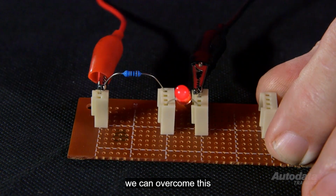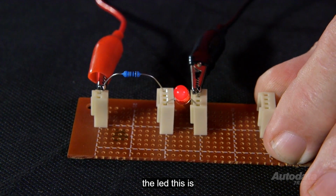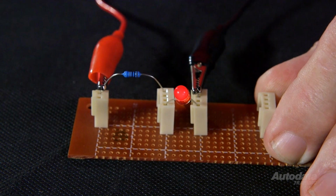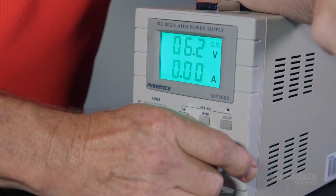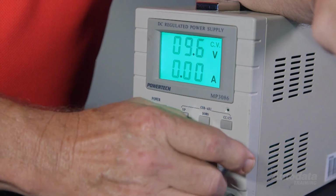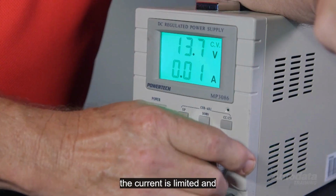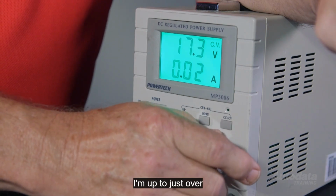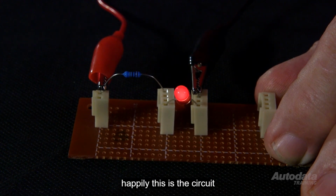We can overcome this by putting a resistor in series with the LED. This is a current limiting resistor. Now if I increase the voltage, the current is limited. And I'm up to just over 17 volts and the LED is working quite happily.